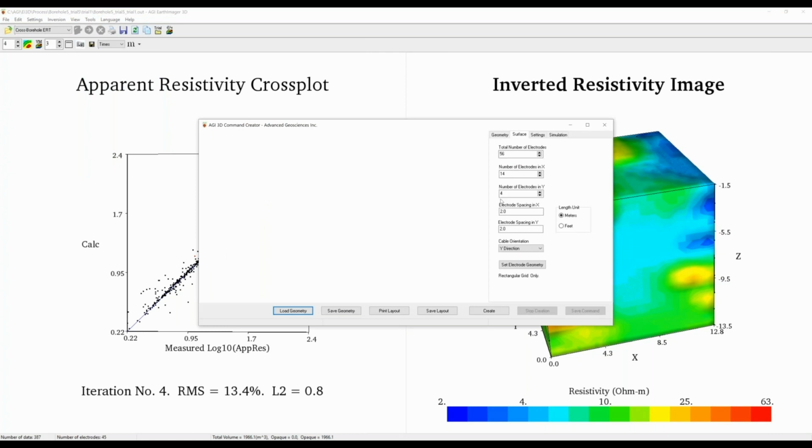If you have an irregular layout, like a square or triangle or surrounding a building, in a special case of electrode configuration geometry, then you need to first create a regular rectangular or square one, and then you can modify it by hand later on.